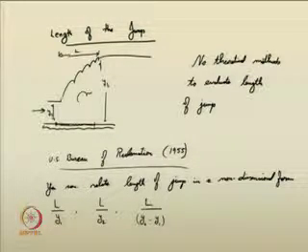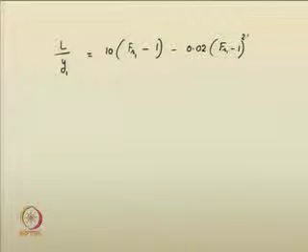As the US Bureau of Reclamation suggested in one of their analyses, the ratio of length of the jump with respect to its pre-jump depth can be given as 10 times (Froude number in the upstream or pre-jump location minus 0.02 times Froude number 1 minus 1) to the power of 2.53. Okay. This was one relationship they developed empirically from their experimental data.